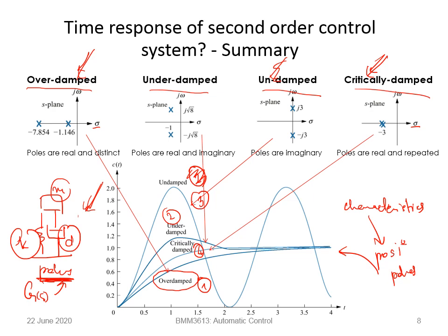So basically that's how a control engineer designs their system. They will have a specification, and the specification will tell whether they could have undulation or not, and how fast the system needs to be. So if they have those requirements, they will design their system, meaning deciding on their parameters M, K and D, so that their poles will fall into one of these four categories, right?